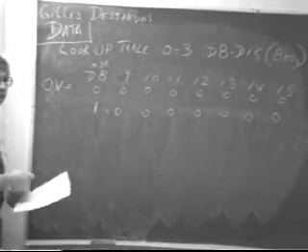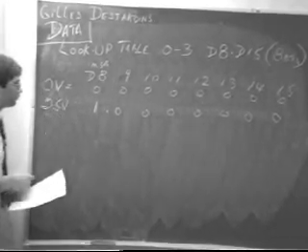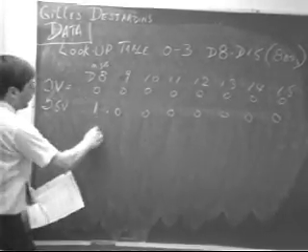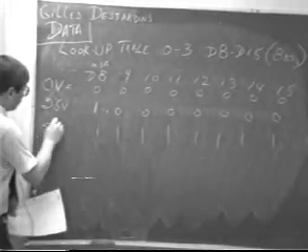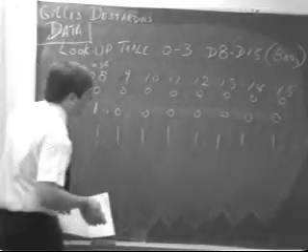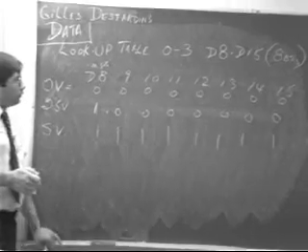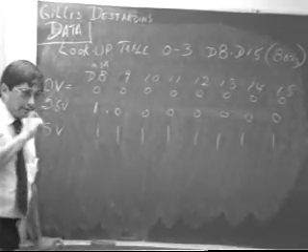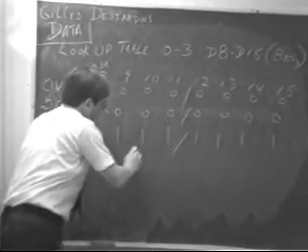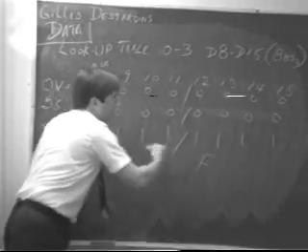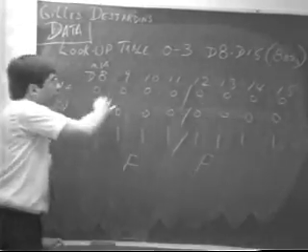When half, so you're going from 0 to 5, this is 2.5 volts. And of course, when they're all 1, 5 volts. You could also represent this in hexadecimal: FF for the bottom one, 80 for the middle one, 00 for the top one.